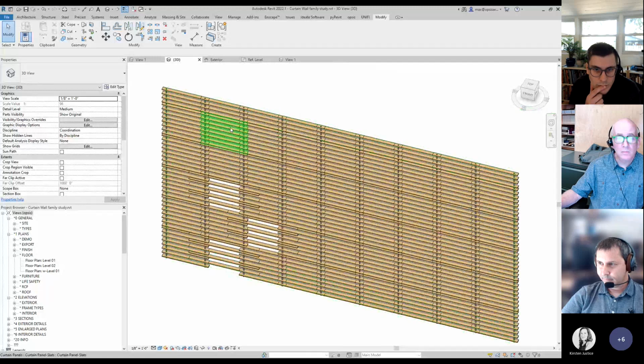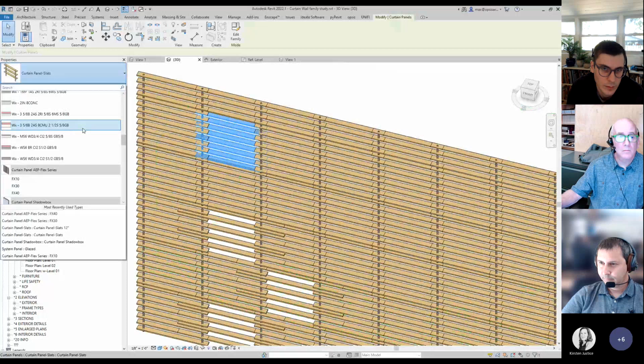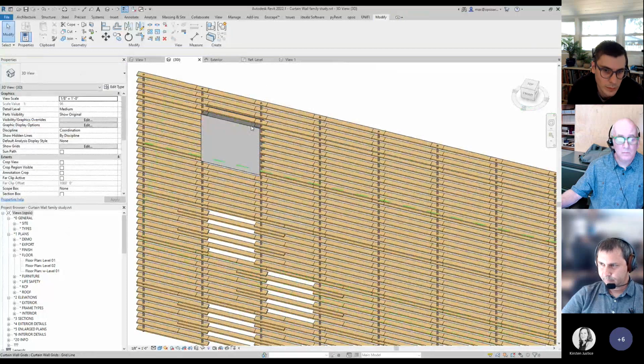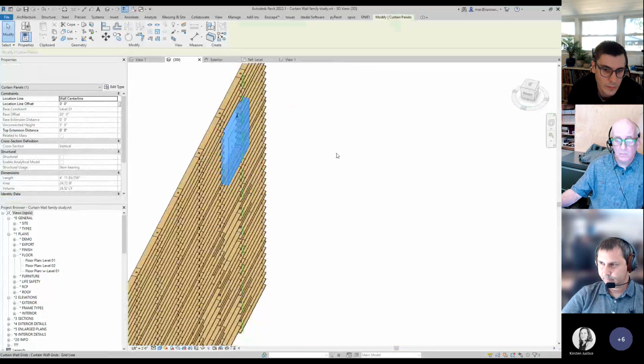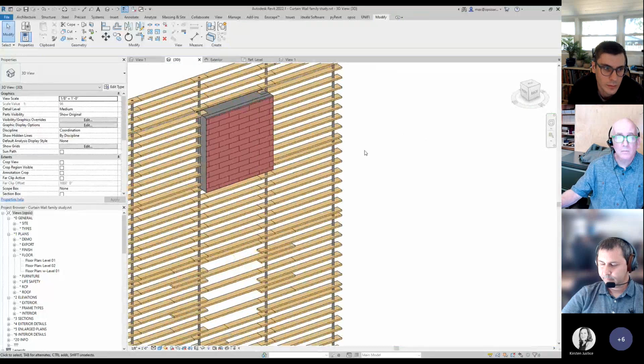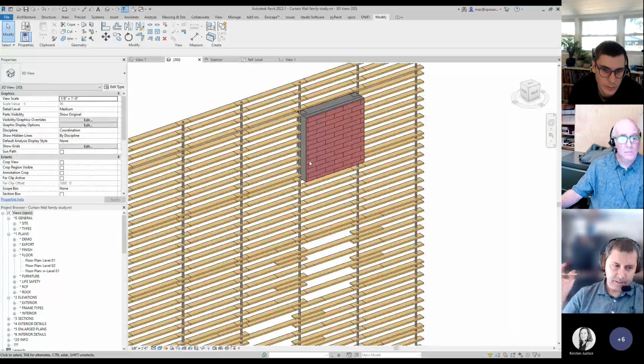But then the thing that I struggle with is when it comes to needing to tag wall types, or tag the different openings as different exterior opening types and all of that. It keeps tagging it all as the same one, but I way prefer to build my exterior walls as a curtain wall, because to me it's just so much cleaner. I don't ever want to go back to building them as separate pieces.